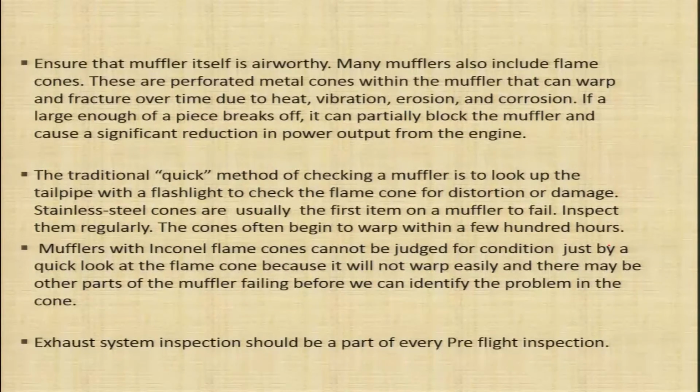Mufflers with inconel flame cones cannot be judged for condition just by a quick look at the flame cone, because it will not warp easily and there may be other parts of the muffler failing before we can identify the problem in the cone. So inconel muffler cones cannot be judged very easily just by looking at them, because they will not warp easily and other parts in the exhaust system, in the muffler, can fail before we can identify the problem in the cone.